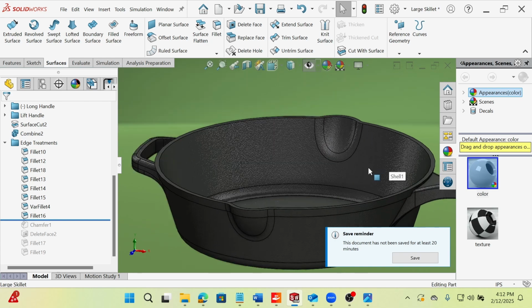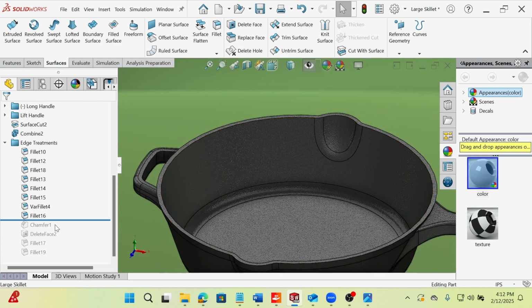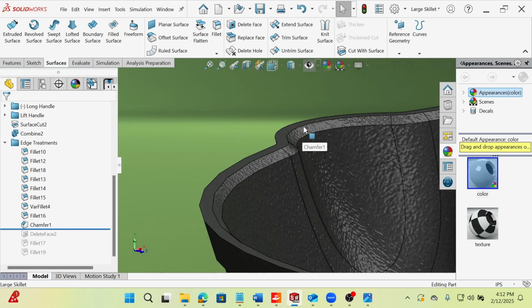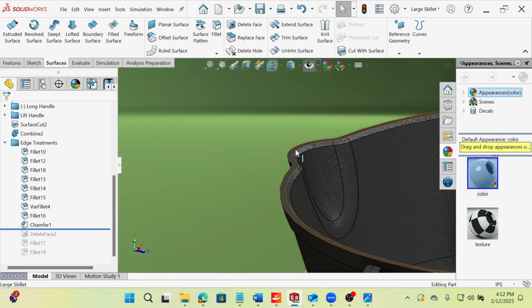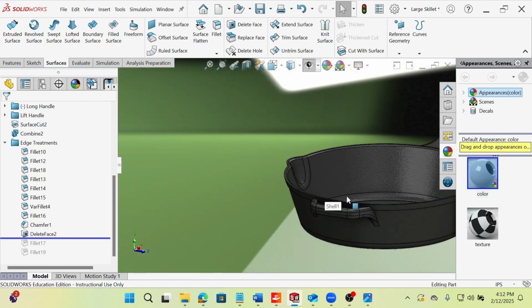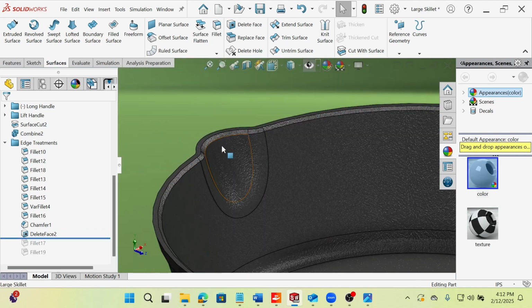Went over this in the spout options demo earlier in the week, but if you are going to have a pouring edge, a wicking edge, I like to have a chamfer on the inside just so it helps to break the water surface tension there instead of a fillet that goes all the way around, super roundy. We may hear something different from the cast iron guys, but for products I've worked on before, that was a good idea.